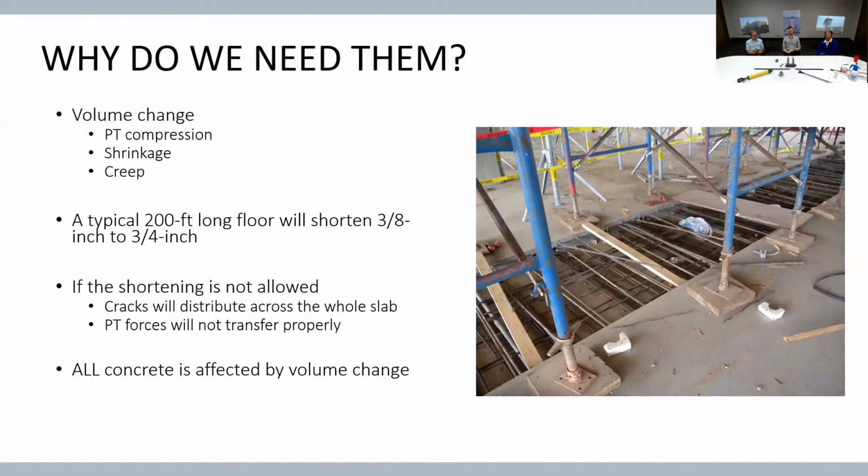And the PT forces that are supposed to be in the slab, we put in typically 150 to 200 PSI in a typical slab. And then the cracking tension is up in the range of, say, 500-600 PSI or something. So if that's in the slab, it takes you having 700 PSI somewhere to crack those slabs. If you have cracks in your slab, it's like, where did those PT forces go? What happened? Well, that's what happens in some of these things, okay?